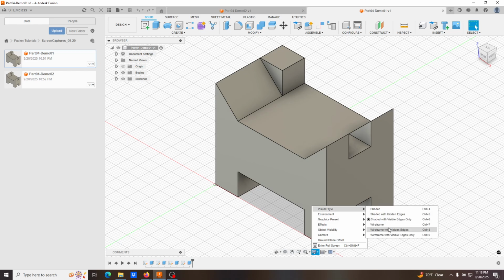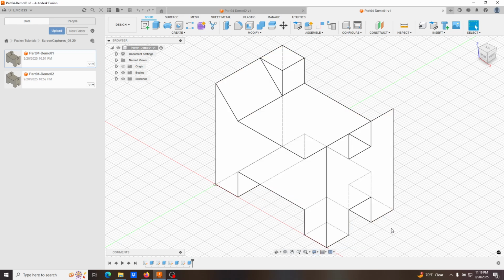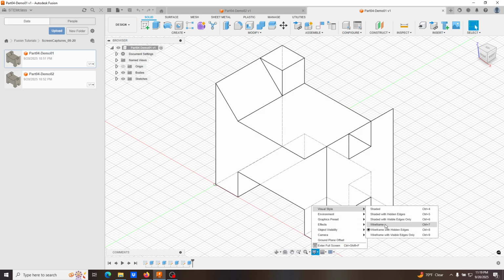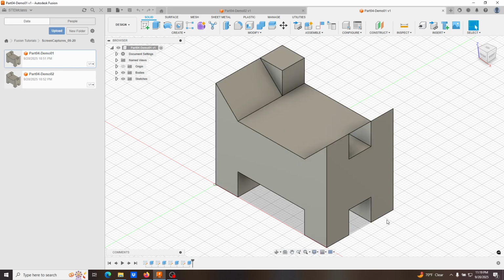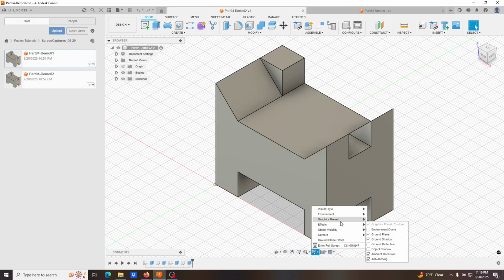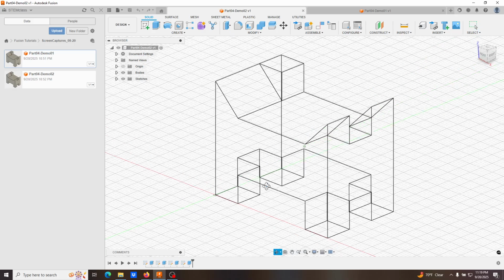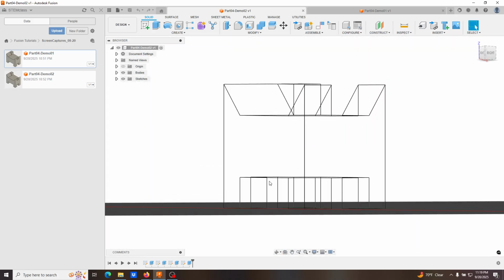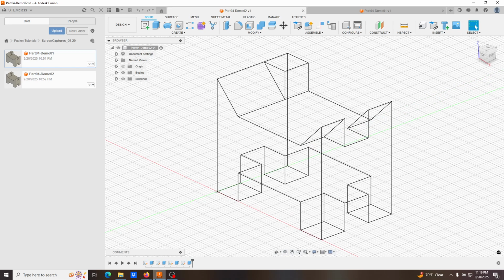there in the back. And so generally, without going too far into it, you'll see you have the hidden edges there. Generally it goes with, if things look like right angles, or if things look parallel, or things look perpendicular, then they generally are. And the idea is that if there was something extra to be assumed there, then it needs to be shown. So, like with this one here, when I go back, the general thought process is that if there was something different from the assumption, then that should be indicated either by hidden lines or visuals or things like that.